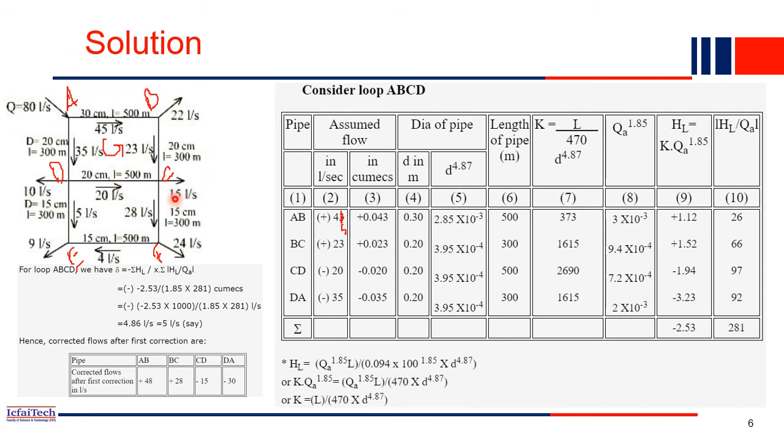So how much will be the flow here? 23 is going into this junction, 15 is going out of this junction, then again 20 is coming in this junction. So 23 plus 20 means 43 is going inside the junction. Then output 15 is going out, and 43 minus 15, you will get 28. So 28 will be going downward. Like that, at each joint we also have to check continuity, is not it?